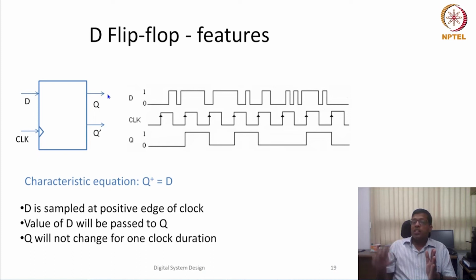Now let's consider further that the output of this adder is used as an input to another D flip flop, which means that the output of this adder can keep on changing during this whole 35 units of time. We have seen this when we did the adder assignment in Verilog code: the output keeps on fluctuating.